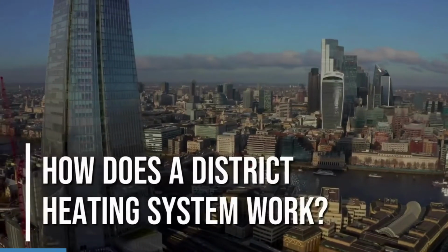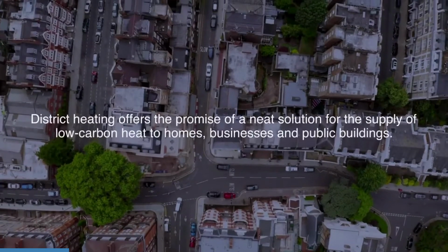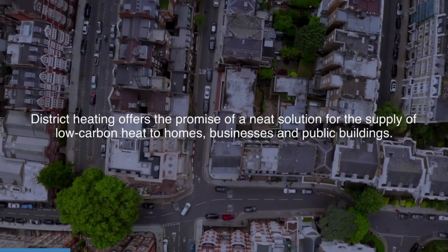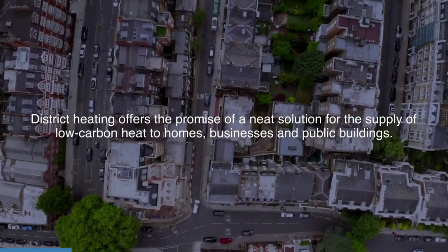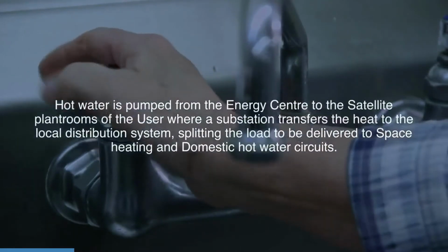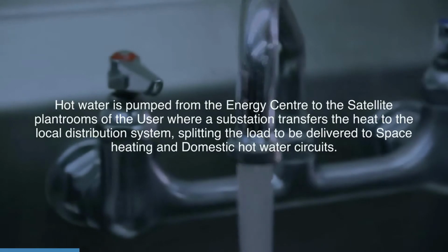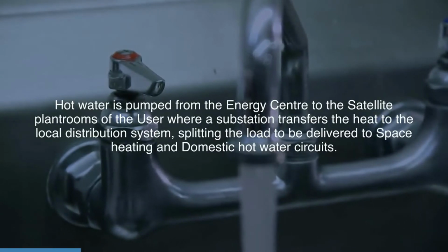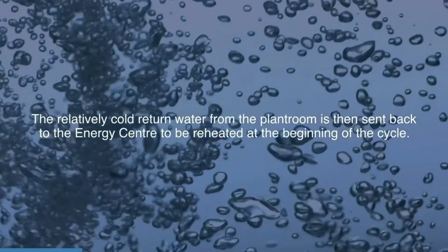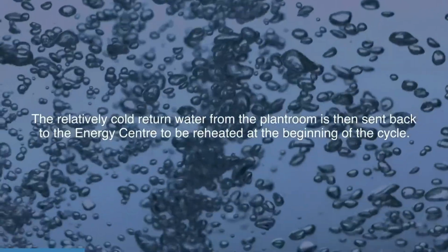How does a district heating system work? District heating offers the promise of a neat solution for the supply of low-carbon heat to homes, businesses, and public buildings. Hot water is pumped from the energy center to the satellite plant rooms of the user, where a substation transfers the heat to the local distribution system, splitting the load to be delivered to space heating and domestic hot water circuits. The relatively cold return water from the plant room is then sent back to the energy center to be reheated at the beginning of the cycle.